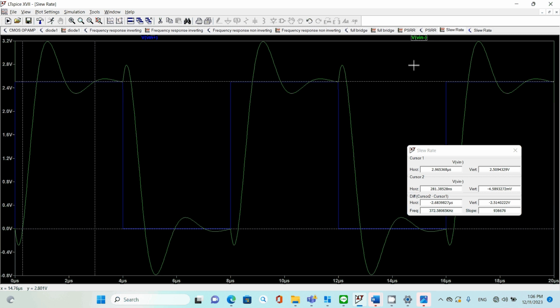Okay, that's the flow for series 1 of the lab EL325, and also the last one will be your PSRR, power supply rejection ratio. That means your op-amp should be able to get rid of the noise signal that comes from the supply negative or the supply positive, because the op-amp's job is to amplify your signal, right?